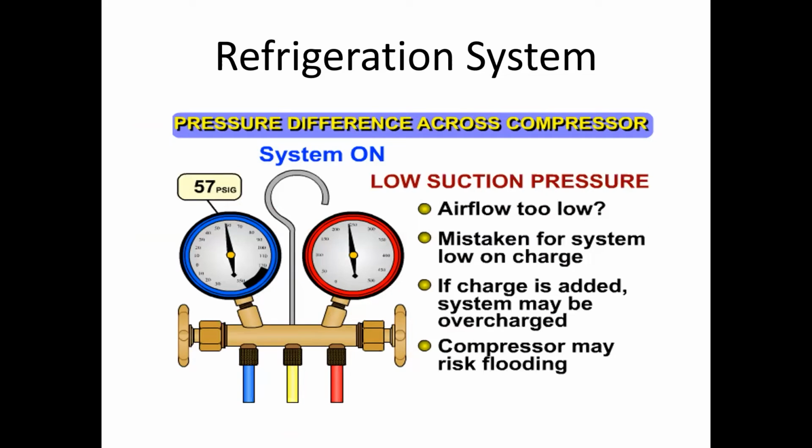So we want to make sure that we have a good pressure differential across our compressor, right? From our suction side to our liquid side, or our suction pressure to our head pressure. A lot of times, low suction pressure is mistaken for a low charge.